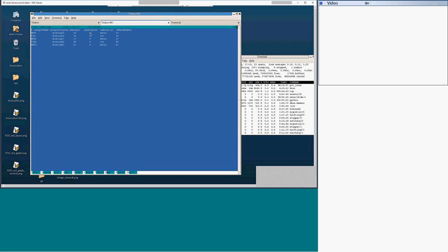That's coming from the process manual of the process, right? I do not know. That's what the customer typically does. The customer figures out what the metal and cut layers in the design are, and then builds this layer map, naming layers from GDS layer numbers and mapping them to OpenAccess mask numbers.